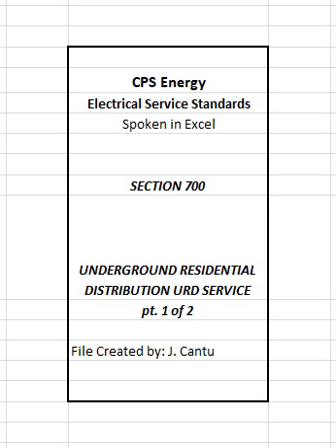2. Pad mount single-phase transformers and associated pads, to be furnished and installed by CPS Energy. Only single-phase, 3-wire, 120/240 volt service will be supplied for URD installations. Refer to Article 703. Exception: with prior CPS Energy approval, customer may elect to construct transformer pads.